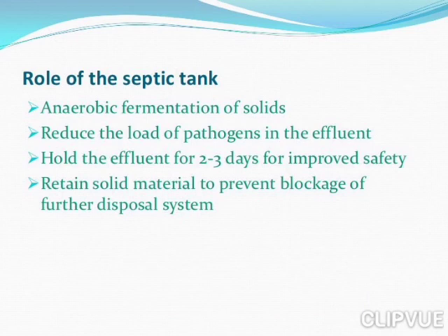The role of the septic tank. Here, anaerobic fermentation of solids takes place. It reduces the load of pathogens in the effluent. It holds the effluent for 2 to 3 days for improved safety. It retains solid material to prevent blockage of the further disposal system.